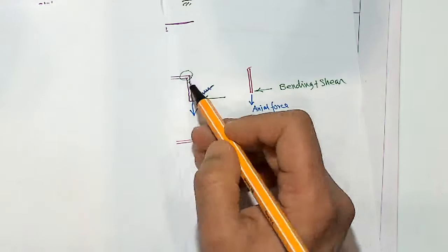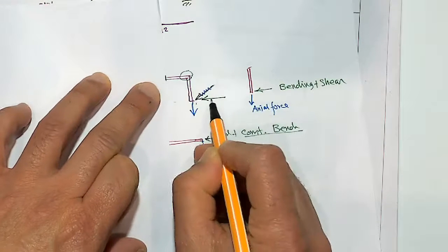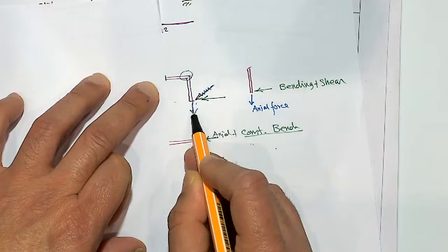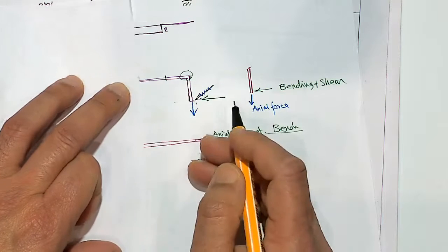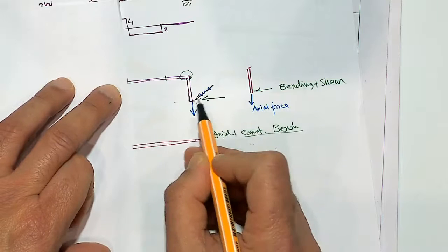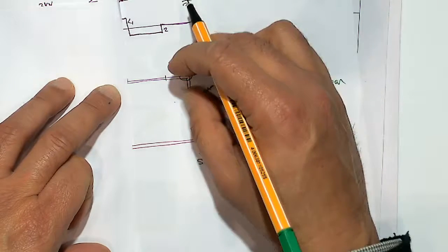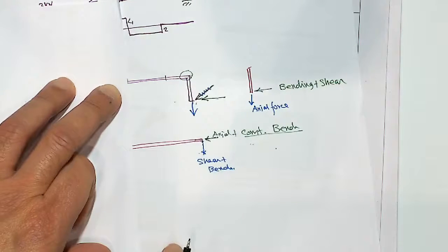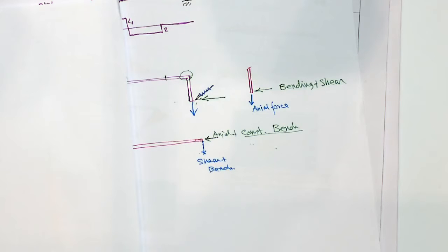So if you take bending moment at this point, what is the bending due to the green? The load times that distance. What is the bending moment due to the green? Blue. The load times this distance. Now take another section here. Bending due to the green does not change because the load times the distance did not change. But the bending due to the blue would change because the distance has changed. So the bending will not be constant along the beam. Okay.